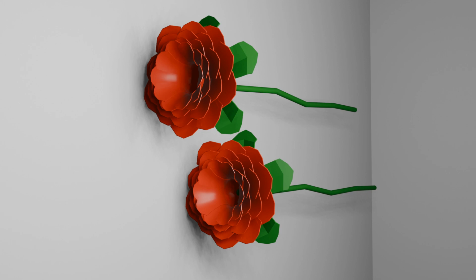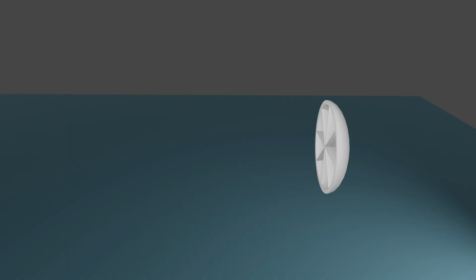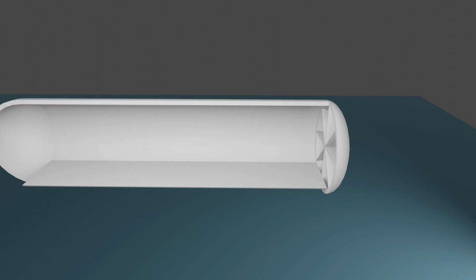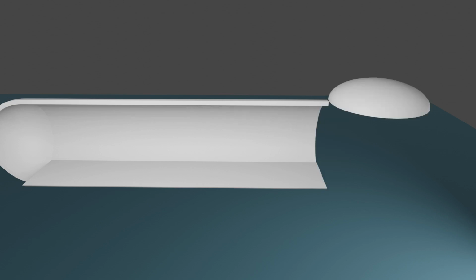At the back of the tubes, a hemispherical closure would be the most structurally efficient shape, but that could not be accommodated in opening the door. There would be no place to put it, so it would have to be flattened. Ribs can be added on the inside to reduce the total stresses and fatigue of the material. The entire rear door would be hinged to open upwards.